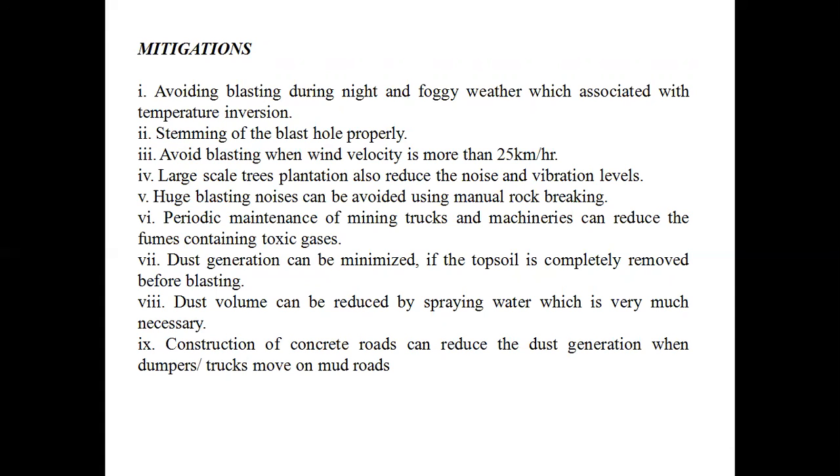Avoid blasting when the wind velocity is more than 25 kilometers per hour; we have to avoid it when the wind speed is too high. Large scale tree plantation also reduces the noise and vibration levels. Huge blasting noises can be avoided using manual rock breaking, so we can do that to some extent.